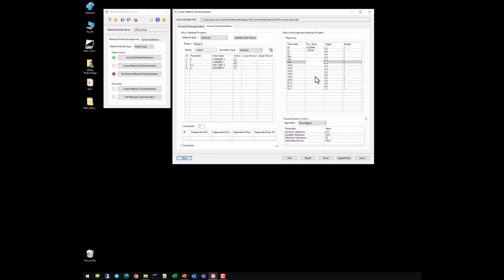The shear modulus GXY is 0.613 e to the 6. My Poisson's ratio in the 1, 2, or XY plane is 0.309. My compression modulus in the fiber direction is 16.284. And my compression modulus in the matrix direction is 1.471.